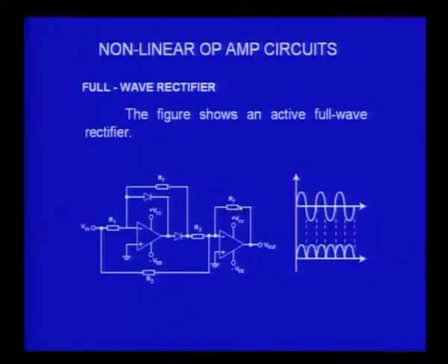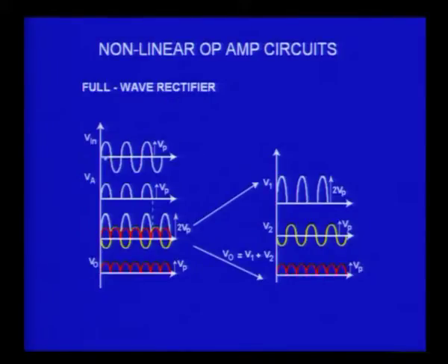Before that, perhaps I should tell you, for example, RF is 2R3, twice R3. The gain factor here for the rectified signal is 2. So, R3, for example, can be 10K, RF can be 20K, and this R2 again here is 20K. That means the gain for the input AC signal is only 1, but the gain for the rectified signal is 2. This is the important point that you should remember. So, with this background, let us try to look at these various signals.